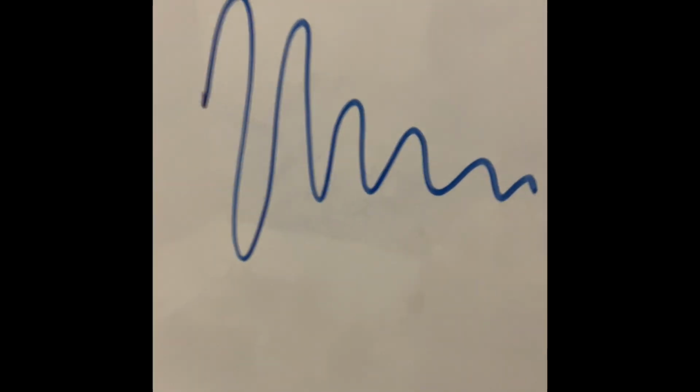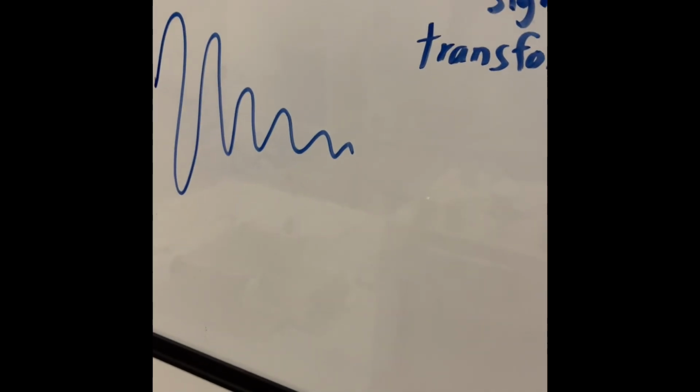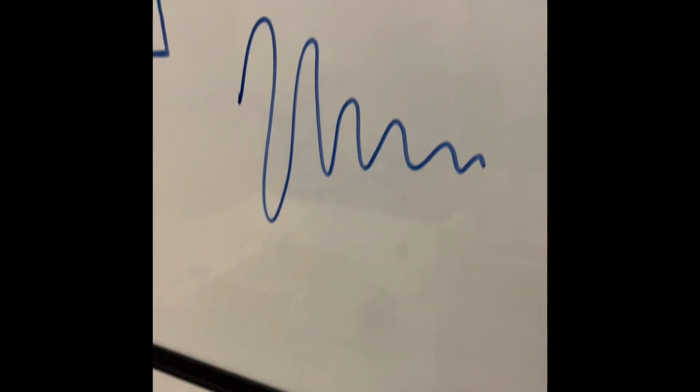So that's the waveform that we're injecting into our primary circuit. And that's what's getting transformed by the secondary part of the high voltage transformer. And we can basically adjust the capacitance to affect the frequency of that modulated pulse.